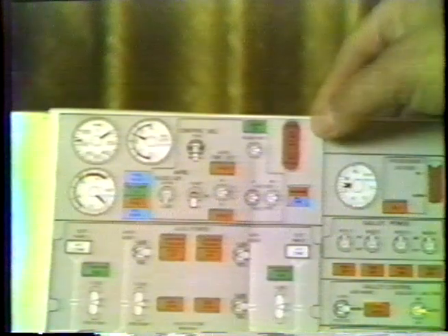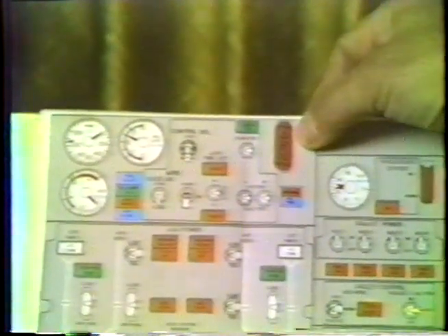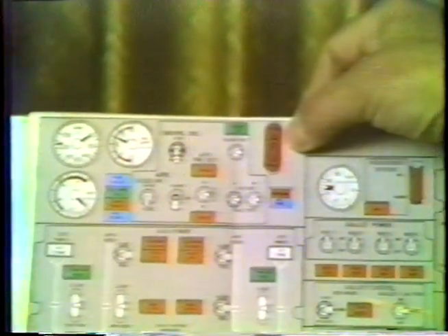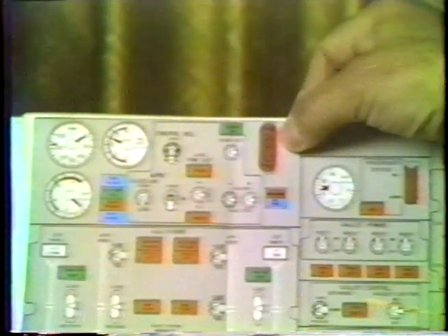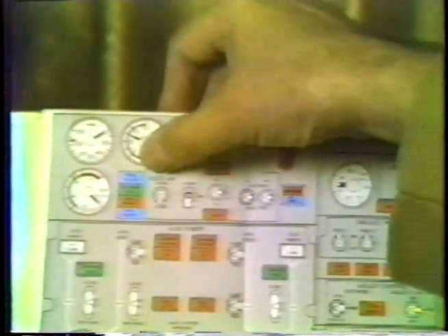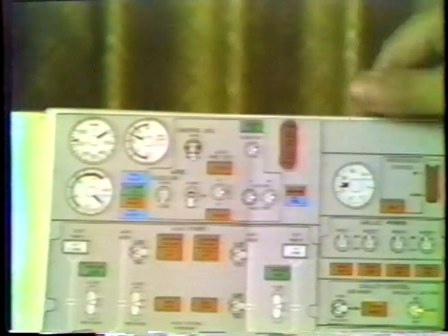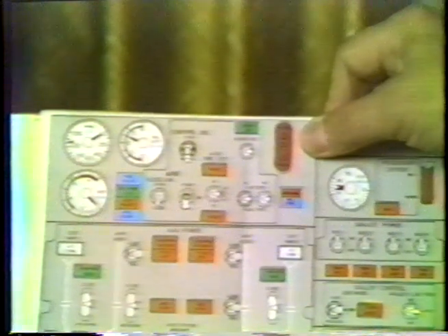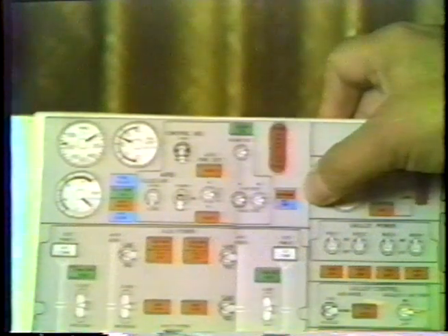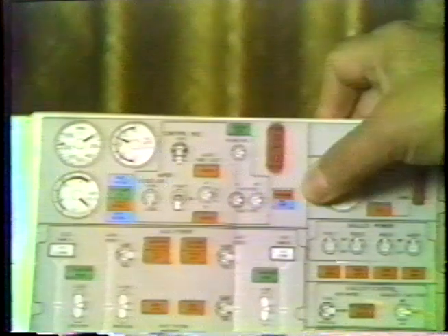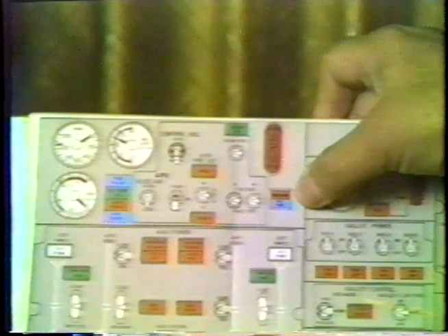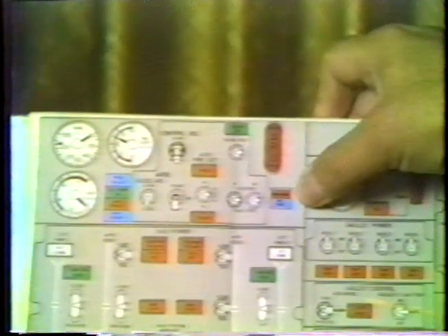If a fire should occur, the APU fire system has already shut down the APU and would have also operated the fuel shutoff valve. So essentially all you do when you pull the fire switch is arm the bottle discharge to discharge the Freon into the APU. The Freon bottle is located alongside the APU back in the tail of the airplane, in the unpressurized portion of the airplane.